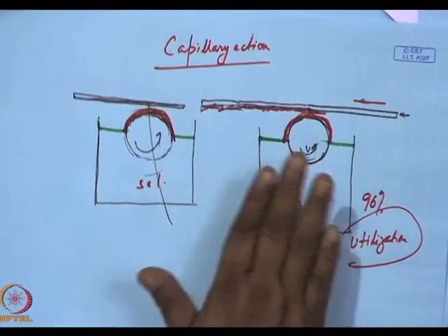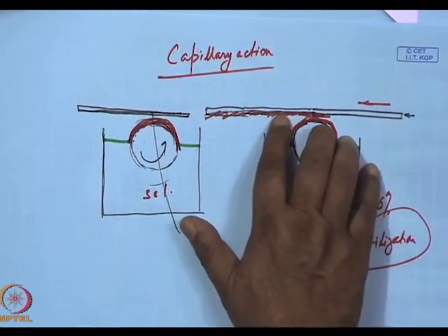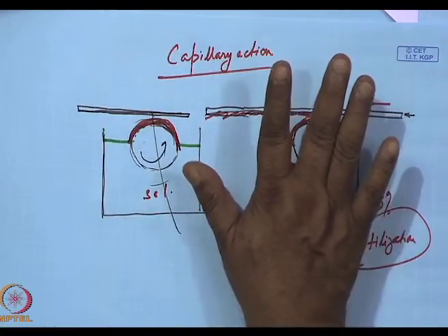Because here I have one bath, I deposit the first layer, let it dry, take it to a second bath, deposit the second layer, take it to a third, deposit the third layer, and repeat the cycle as many times as we want. If we have good control over the modeling aspect, the viscosity, the temperature and the evaporation rate, we are now able to generate multi-layer coatings using sol gel technology.